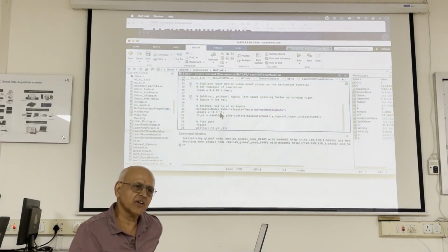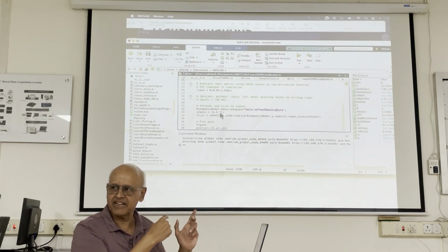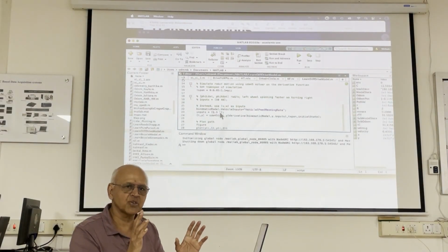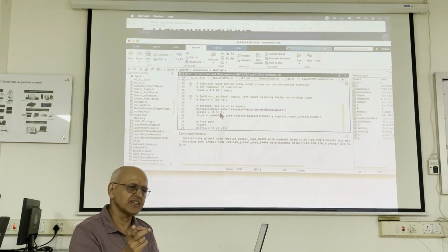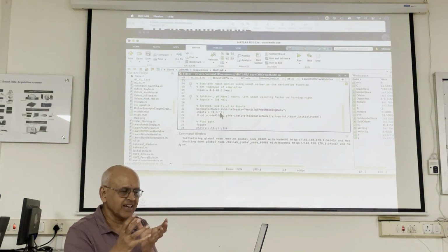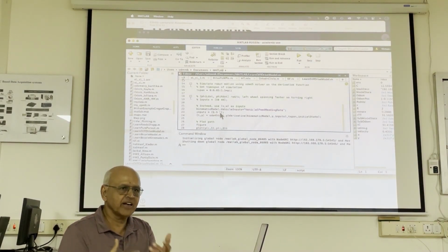So this is a software object. You can make this move forward at 500 miles per hour and nothing will happen. This is MATLAB, it's just implementing those equations. It can go as fast as you want it to go, it will be fine. The Gazebo robot is different. Those are meant to be simulations of real robots. So if they have put those features in, you'll find it doing strange things. It might even topple over.